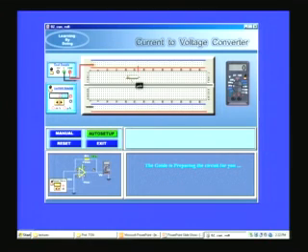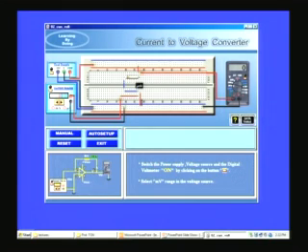So the IC is put there, the resistor is put there, and the different wiring are done corresponding to the circuit, and the circuit is shown here. It is a very simple circuit, 2 inputs and 1 feedback resistor between the output and the input, that is all. So that pin number 2 is connected to pin number 6, that is a feedback loop, and the value of the resistor is 10 kilo ohms typically in this case. So you have the voltmeter here, you have the dual supply, all the things.